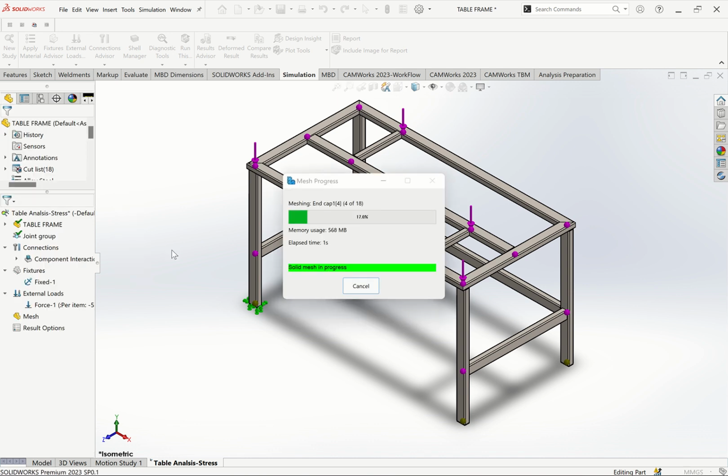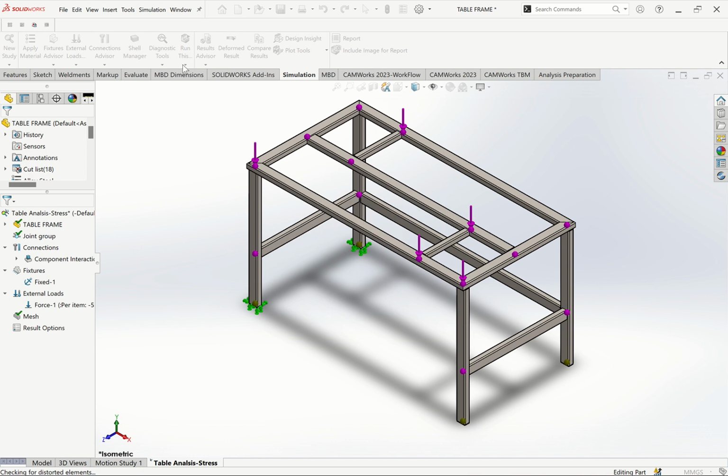So let me mesh. First of all, okay, create a mesh. After meshing, it takes time. That's the problem with meshing, because I've put it so fine, that's why it may take a lot of time to do meshing across regions. And also remember, I've not done welding, so in case I do welding, I also ensure that the accuracy of the results increases. But let me do it first, and then I'll add welding, then I'll see if that contact area will affect my result. Okay, then I can go to